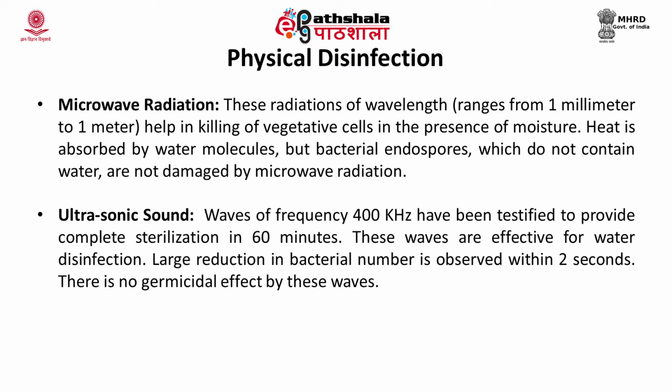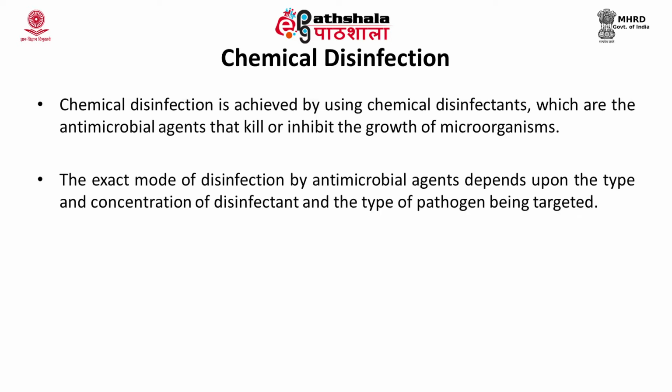The next kind of radiation is ultrasonic sound, where waves of frequency of approximately 400 kilohertz have been testified to provide complete sterilization in 60 minutes. These waves are very effective for water disinfection. There is no germicidal effect of these waves, but a large reduction in bacterial number is observed within 2-second exposure of wastewater. After the physical processes of disinfection, now let us discuss the chemical disinfection process.